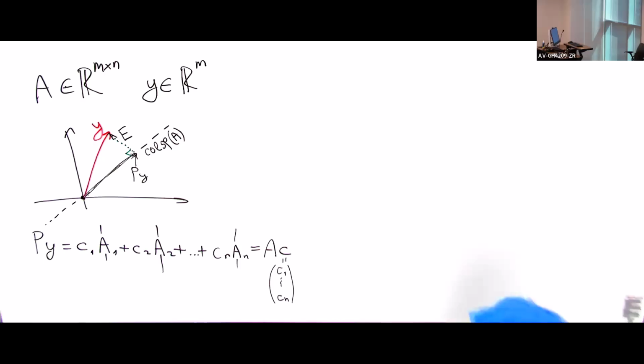Okay, so you can represent that thing as A, and you need that P to be a matrix, right? So to be a matrix, you introduce some new matrix. That C will be some matrix times Y, because you know that on the right it needs to be multiplied by Y somehow, and on the left it needs to be multiplied by A. So there is something in the middle that you don't know and needs to be determined. So matrix K needs to be determined here.